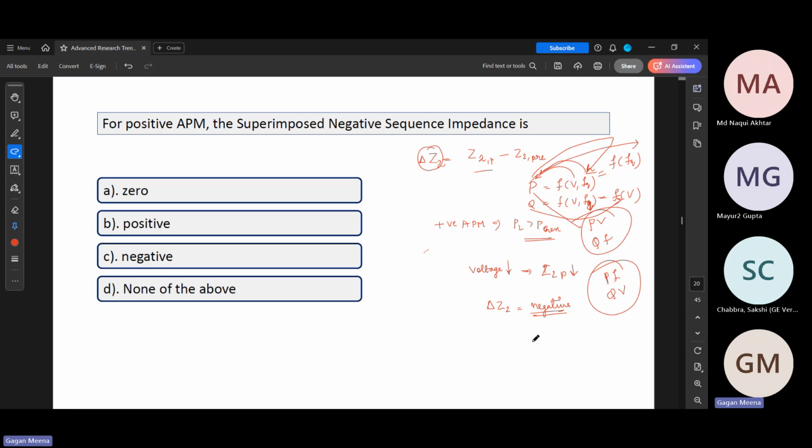In fast decoupled power flow, we have P and Q here, and voltage and angle here. We say we have only theta and V here. So theta is directly related to frequency and this is voltage. So we have here B dash and B double dash, right? So here there is a direct decoupling.